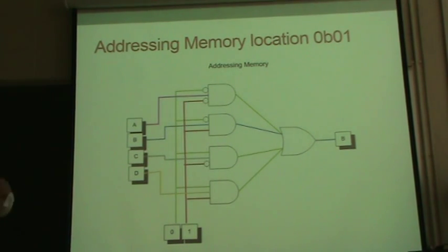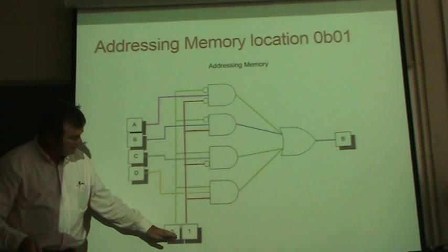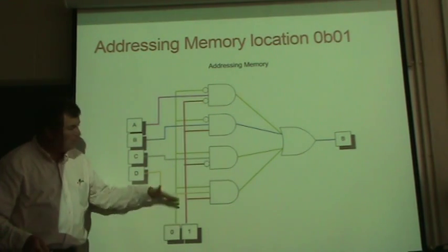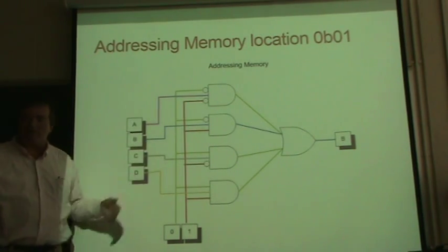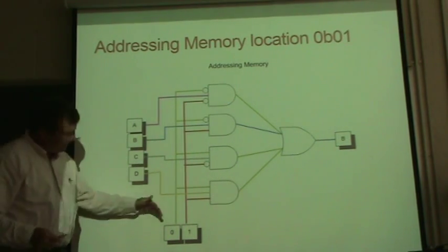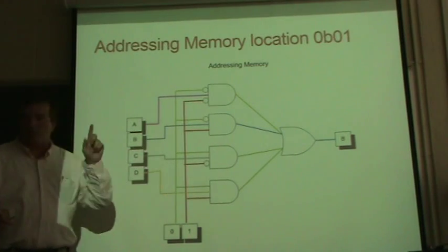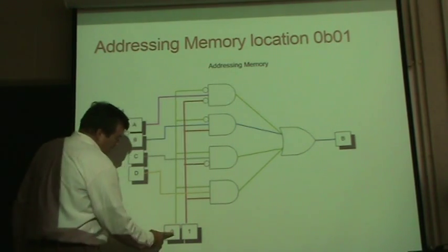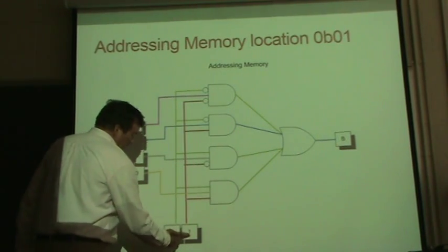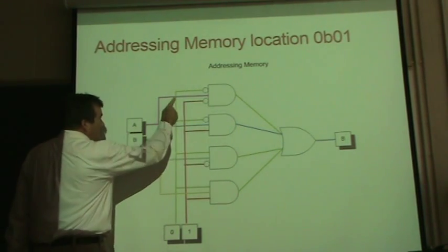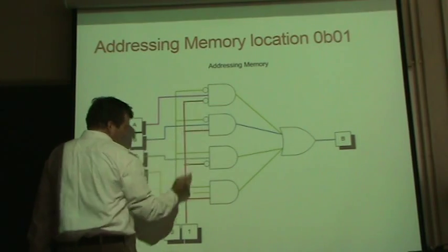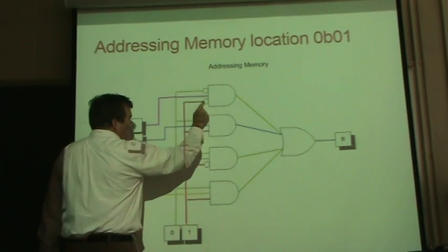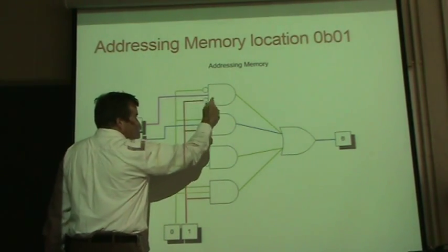A decoder was a piece of hardware that if you put a value here, it'll tell you one and only one of the 4 possible outputs. And if we had 3 bits, it would be 8 outputs, and we turn one and only one of them on. So, in this example, I set the decoder value to 0 and 1. So 0 comes up here, and runs into here, that's a 1, and this 1 comes up here, runs into this NOT gate, and becomes a 0.